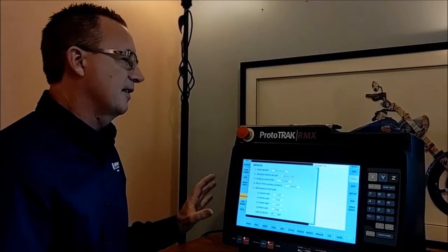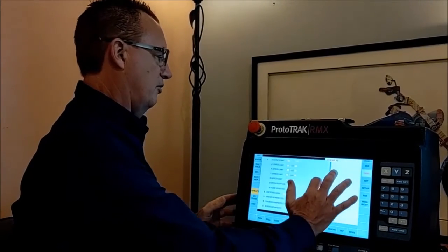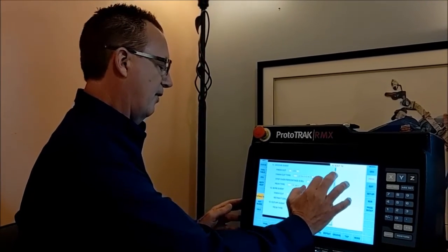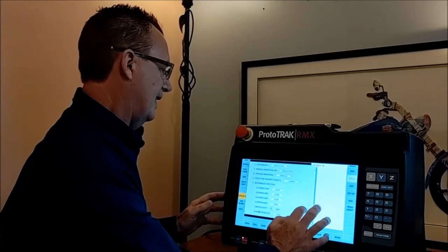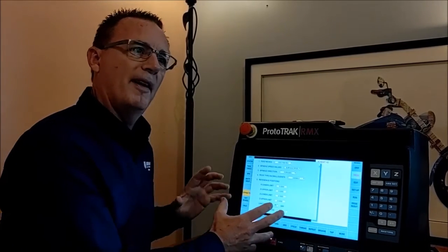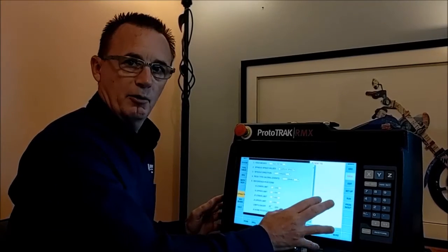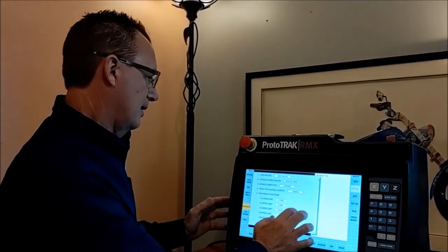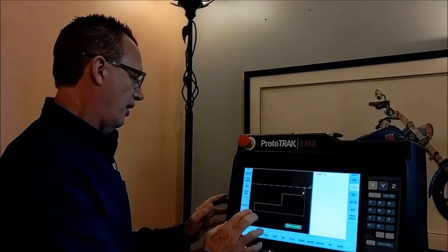The defaults, this is new to the RX control. The defaults are user defaults. You can see I'm scanning down through here, and on the lathe there are 13 different categories, and I can manipulate or set these according to how I like the machine set up. So basically what we do is teach the control how we like the machine set up, like how much we might leave for finish, et cetera. So this is a new addition to the control. It's a great thing to have.